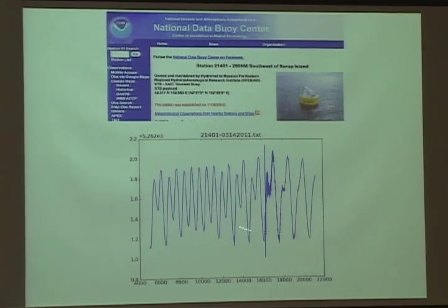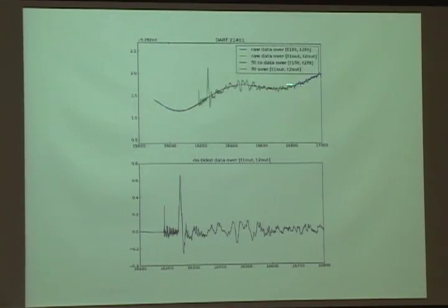So if we blow up the time around the tsunami, it looks more like this. And then if you remove the tide signature from that, you get the tsunami itself as it goes past this particular point, looking like this. And notice that this was a very big tsunami, but this is only 0.6 meters above the tide. Actually, this is the main tsunami wave here. This noise that you see before is actually the seismic wave going by, which travels through the Earth much faster than the tsunami does, and the resulting noise behind that.